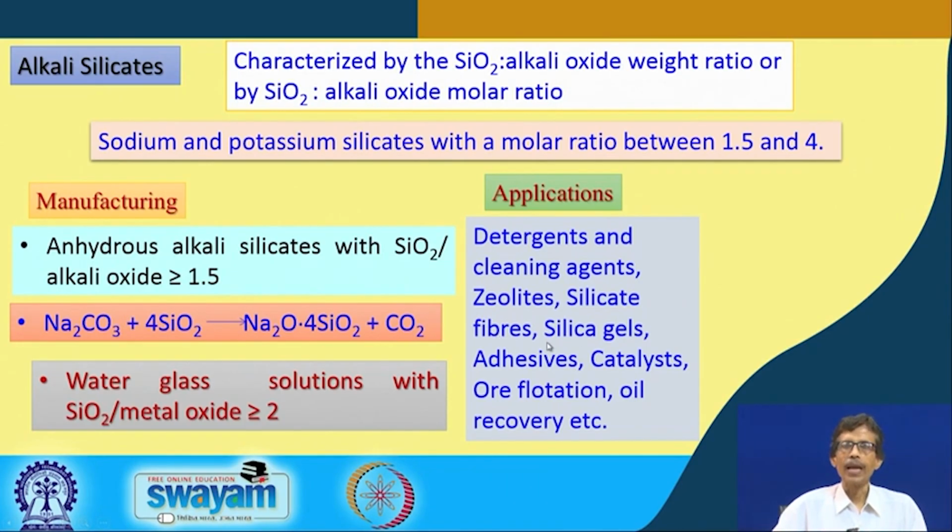Silica gels we can have, and silica gels are the typical dehydrating agents, of different types. Sometimes it can be impregnated, that means cobalt compounds are deposited, which gives colored silica gel, because we put these silica gels as a dehydrating agent in the desiccator or as industrial desiccant material.